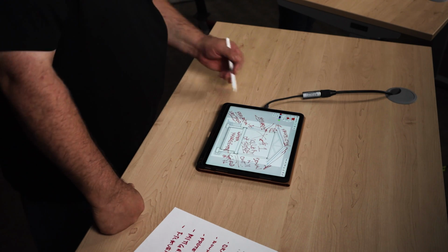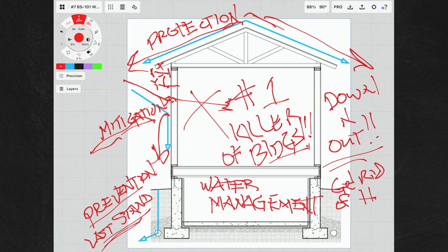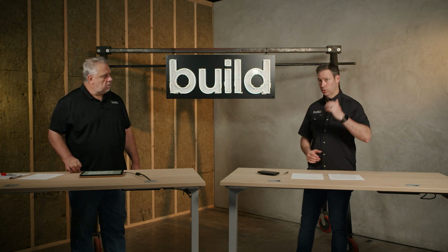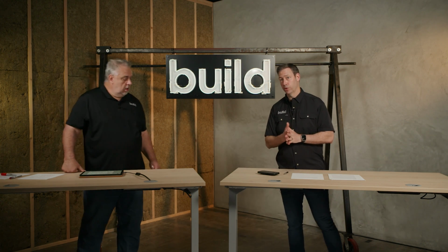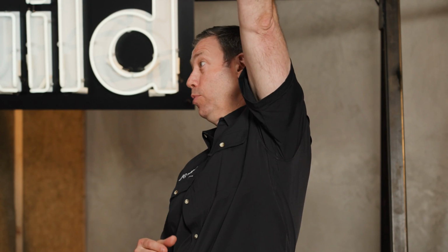I've seen that a lot as well. Unprotected. So that aspect ratio, in my buildings, if I want it to be a very favored condition, I want it to be 2 to 1. So 2 foot overhang, about the top of the window, about a foot below it. Got it. And that 2 to 1 really gives me really good protection. Which also means that if you've got a 2-story house, this is maybe a 1-story that you're showing on this diagram, but if it's a 2-story house and that overhang's way up there, maybe 20 feet in the air, those first floor windows are pretty exposed.